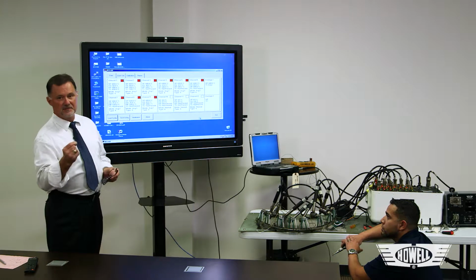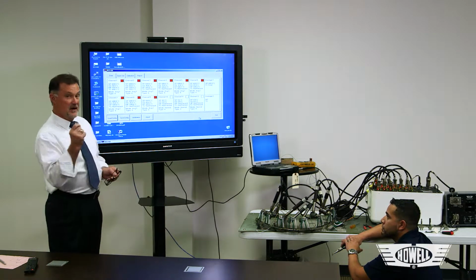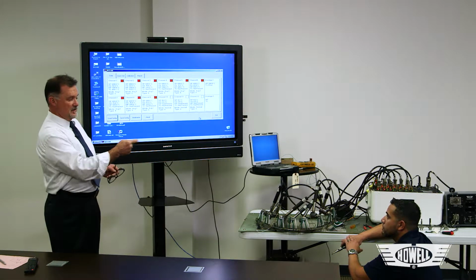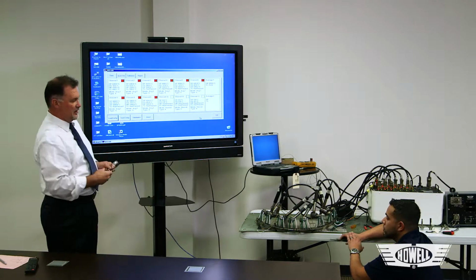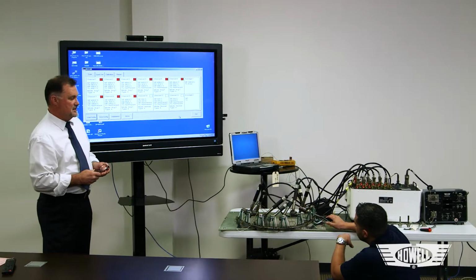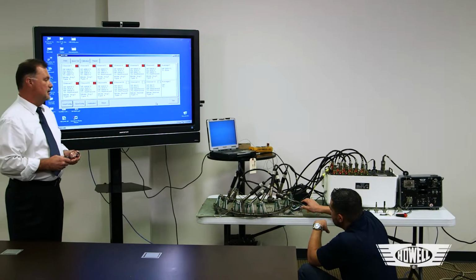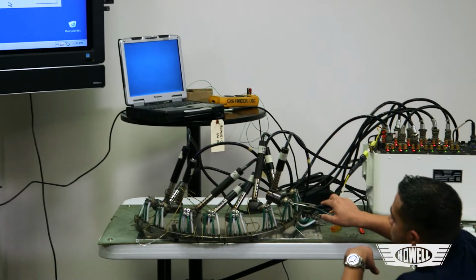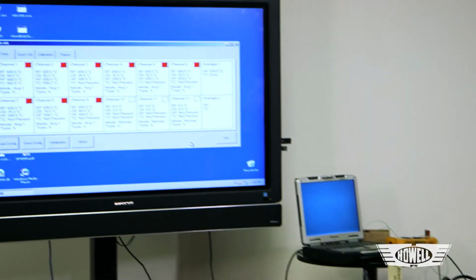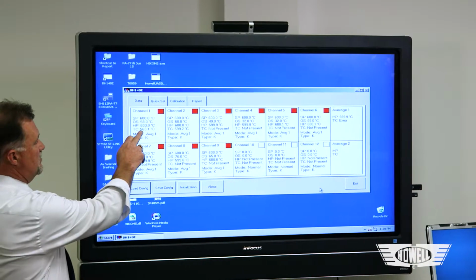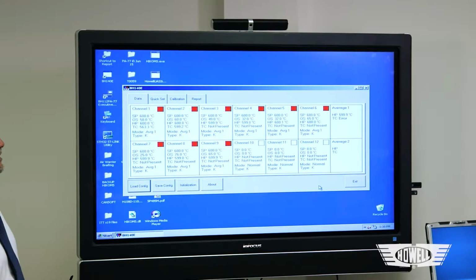Probably one of the most susceptible places is inside the thermocouple, but it also can occur at the aft on the lugs. So for our ease, so we don't get burned, I'm going to ask Steve to go ahead and short out the TIT thermocouple on thermocouple number 2. Number 2. Okay, thank you, Steve. And as you can see now, significant impact. We're down to 563 degrees.